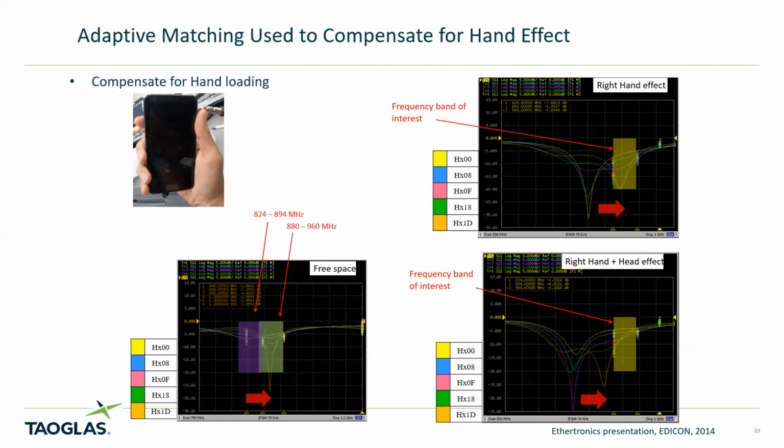And here are some slides to highlight, again, a smartphone. The main idea was that, due to the crowded volume in that smartphone, there was not enough room for a well-sized antenna. So the idea was to take a narrow band, low band LTE response and tune it from 824 to 894 or 880 to 960, kind of that flip between bands 5 and 8.